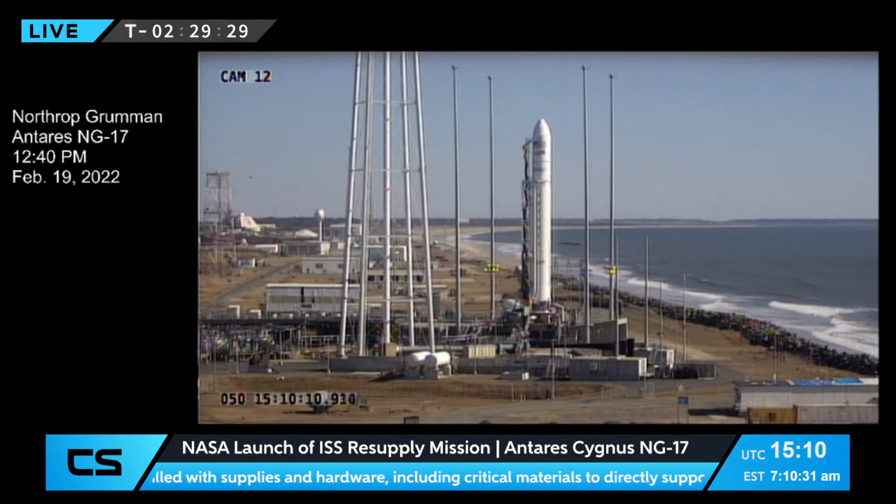We've also completed all of our FTS testing and SNA arming. We have left to get through our EHS functional testing, but that will require pad clear, and we'll have to wait till we get Red Team out of the pad before we can press on that. We have enabled our warm helium system as well, however, we are going to hold off on charging engine bottles until we are able to clear personnel from the pad.